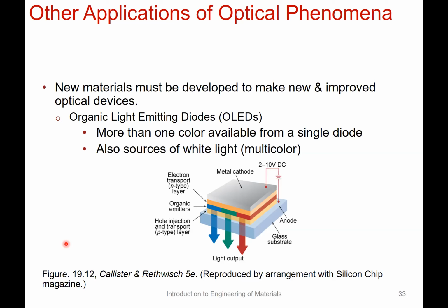photovoltaic cells, solar cells, where we can excite a material like silicon, what we talked about, amorphous silicon, crystalline silicon, heterojunctions, where you have different layers of compound semiconductors like gallium arsenide, and then other layers like amorphous silicon, and then crystalline silicon and all that. So you can make a whole stack to make your solar cell more efficient. But basically what you really want to do is utilize a wide range of wavelengths and make your cell more efficient, as opposed to having one type of material and then it's sort of locked in on one efficiency, and that's the Shockley-Queisser limiting efficiency.